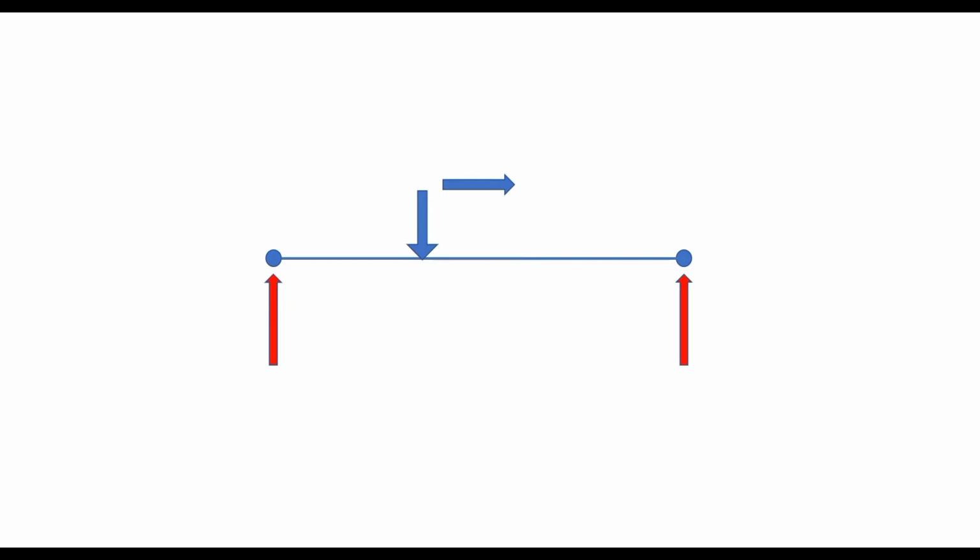While there is no problem balancing the vertical load, the horizontal load will not be balanced unless we have at least one node having a support capable of developing a horizontal reaction. So we see that we would at least need three reactions to be developed to lend a stable configuration to the system against a general applied coplanar system of forces.